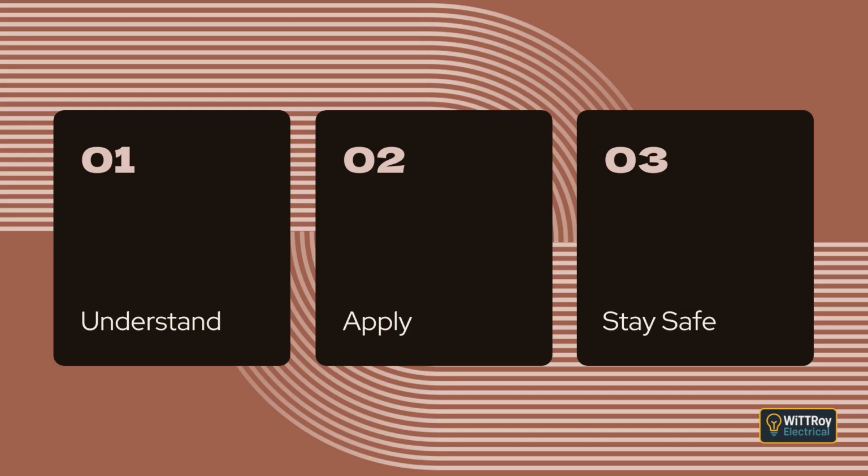Clause 2.3.7.1 General. Functional switching is used when we need to control equipment in the normal course of operation. For example, turning lights on or off, controlling motors, controlling appliances, or switching different functions of machinery. A functional switching device must be provided for each part of a circuit or each piece of equipment that needs to be controlled separately from other parts of the installation.